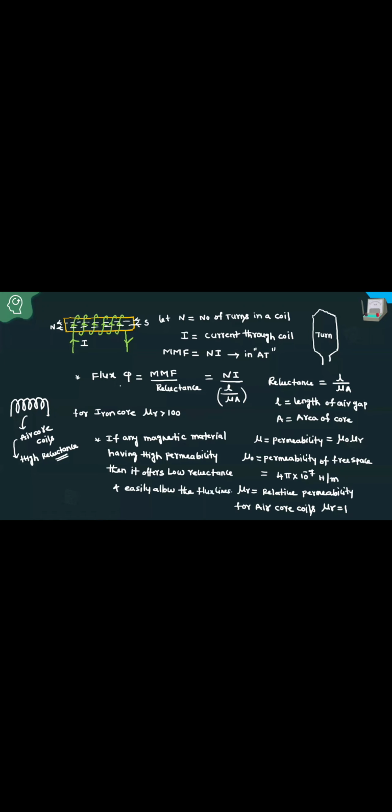It is flux. What are the units of flux, friends? The units of flux is Webers. Then once you know the flux, now you have to calculate the inductance, friends. Then before calculating the inductance, how to define the flux density? Can anybody say? How to define flux density, friends? The flux density B equal to flux per unit area. The flux density equal to phi by A. Then what are the units of flux density? The units of flux density is Weber per meter square.